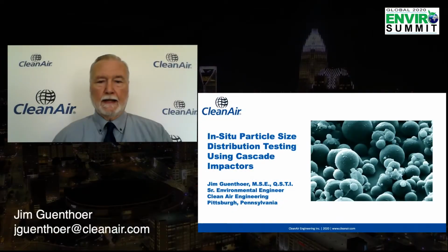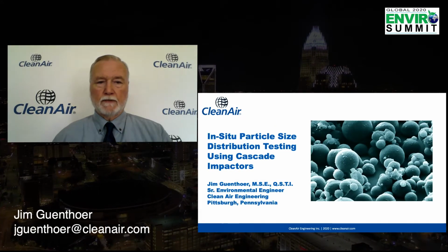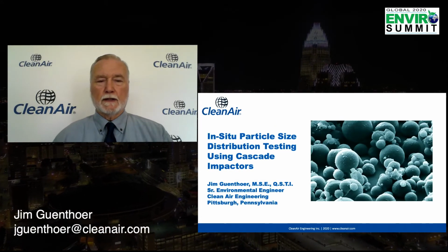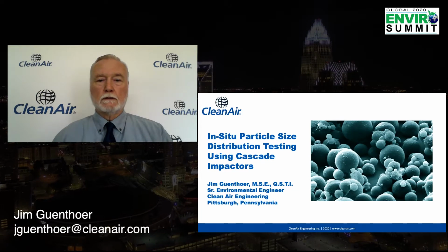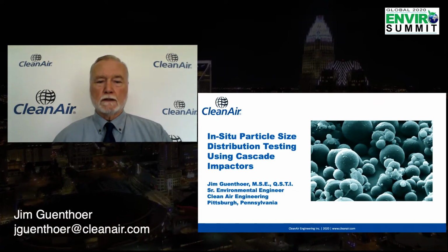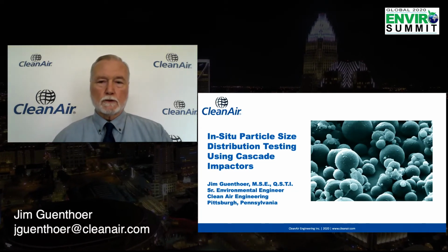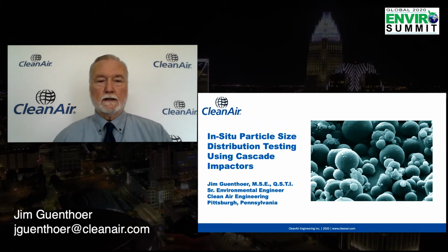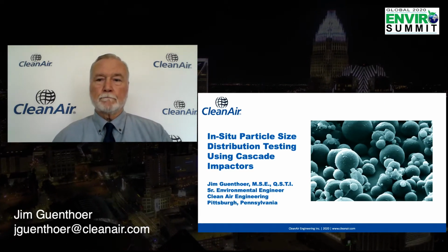Today we're going to look at in-situ particle size distribution testing using Cascade Impactors. It's a long-established air measurements protocol, and it is not as widely used, but it can provide us with some really good information about the operation of air pollution control equipment and processes and their size distribution.